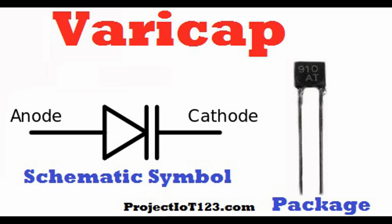Voltage-to-frequency conversion. VCOs are used in applications where an input voltage needs to be converted into a frequency output, such as in sensor interfaces. 6. Types of VCOs. LC oscillators. VCOs based on inductor-capacitor (LC) resonance circuits are commonly used in RF applications. Ring oscillators. Ring oscillators consist of an odd number of inverters connected in a ring. They are simple and often used in integrated circuits.